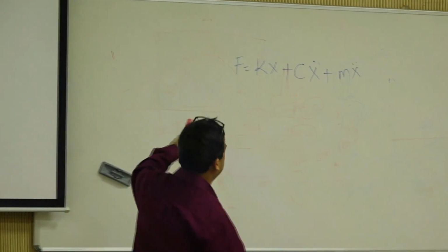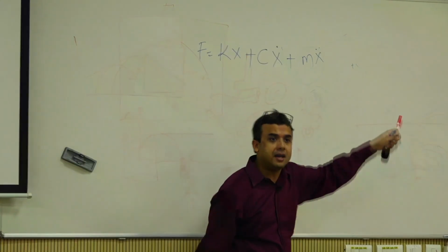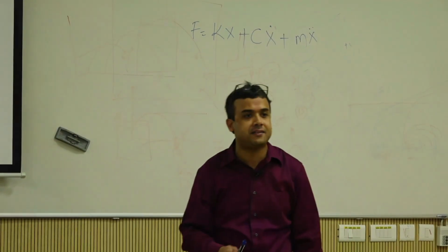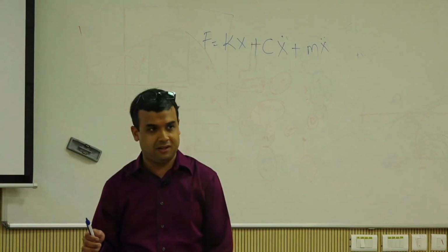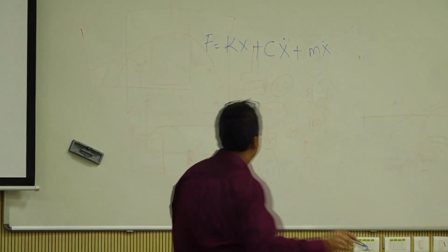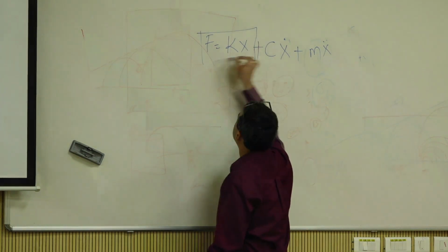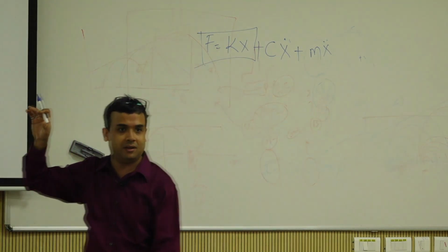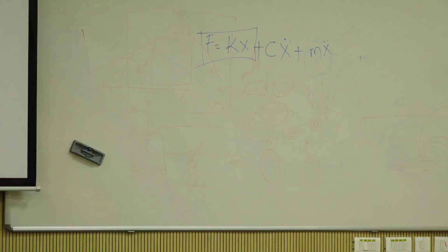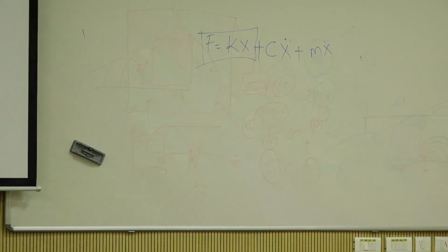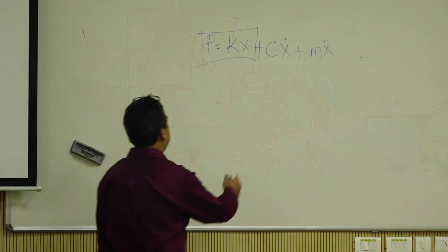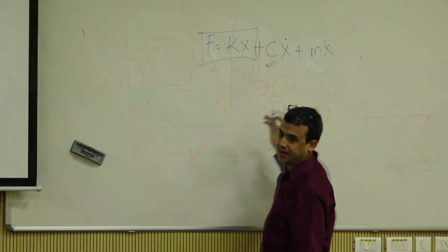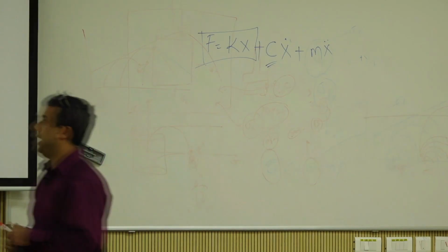If you are analyzing test data in a real dynamic situation, then you have to consider the inertia effects, and you have to consider damping effects. In resilient modulus testing, whenever we go into that, you will see we are still simplifying it only to the first term. It is a repeated loading test, but we are not doing a true dynamic characterization. So it's not a dynamic property. Modulus testing is not dynamic, because you are not considering the effects of damping, rate dependency, the inertia, and stuff like that.